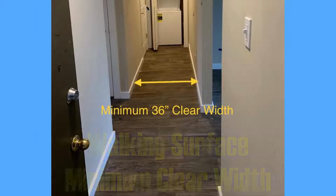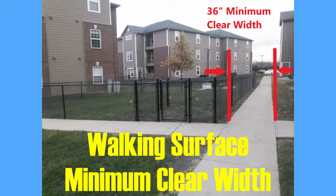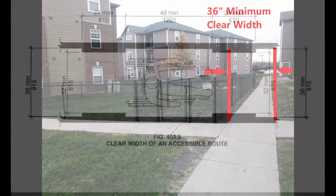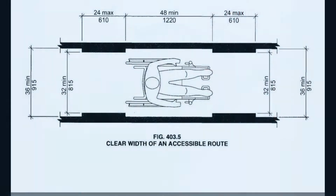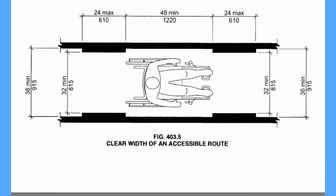The minimum clear width of a walking surface is 36 inches. The clear width shall be permitted to be reduced to 32 inches minimum for a length of 24 inches maximum, provided that reduced width segments are separated by segments that are 48-inch long minimum and 36-inch wide minimum.